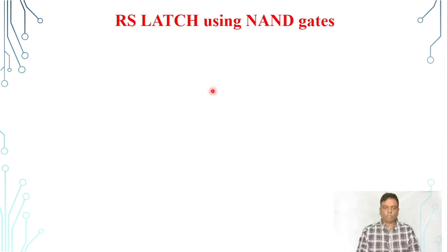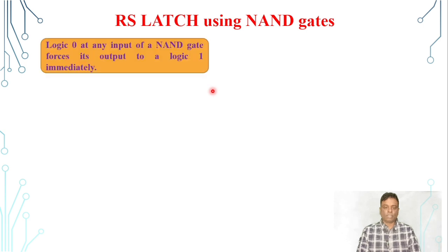So what is the speciality of this NAND gate? Logic 0 at any input of the NAND gate forces the output to be logic 1. If any input of the NAND gate is 0, it forces the output to be 1. So this is a NAND gate.